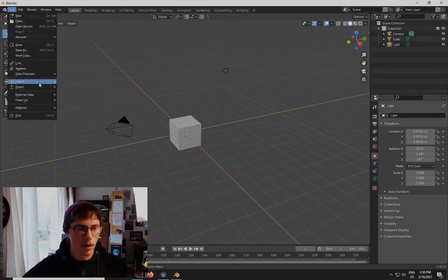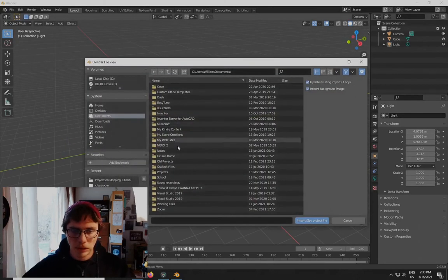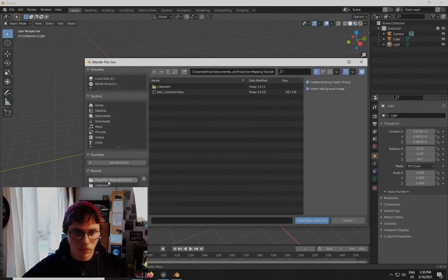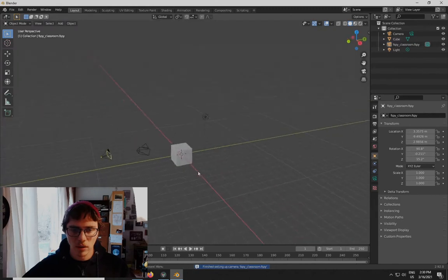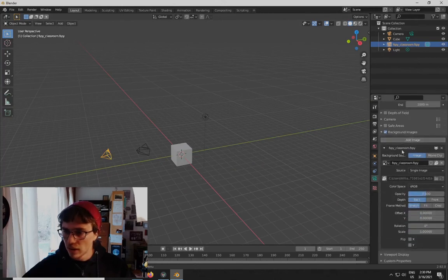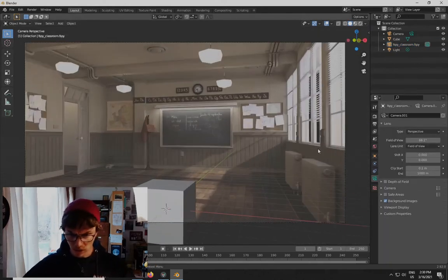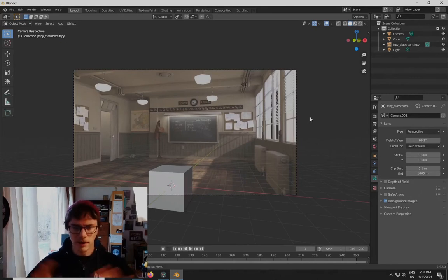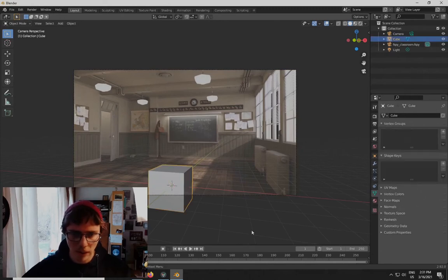Again, you'll need the Blender add-on, but we're going to import that fSpy file that we just generated. fSpy Classroom. So what has this just done? It added a new camera to our scene, and that camera, if you look at the camera settings, has background images enabled, and it has loaded up the image out of the fSpy file with the correct camera dimensions that it calculated. That's all stored in the fSpy file. Our camera is now calibrated to fit in the scene.